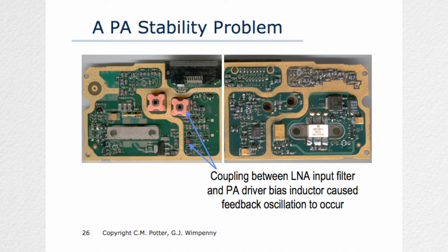So a lot of passive parts in this region here are actually switching between the two possible antenna connections, internal or external. And it's also connecting between receive and transmit. So the transmitter output goes this direction, and actually the receiver input, the LNA, is over here, and there's some input filtering here on the other side of the board. So from antenna through to the receiver, or from transmitter out through to the antenna, is handled by some discrete switching.